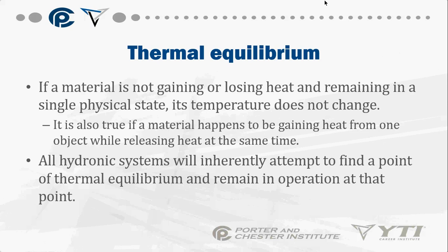Thermal equilibrium. What device on there is going to try to help maintain this? It's not the balancing valve, is it? Nope. Begins with an A. Aquastat? Yep. The aquastat is going to help a hydronic system try to find and maintain a certain temperature or thermal equilibrium